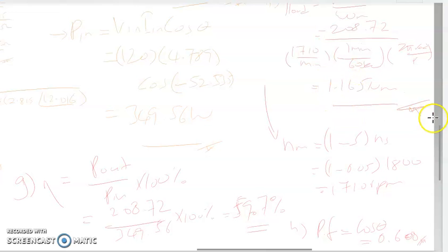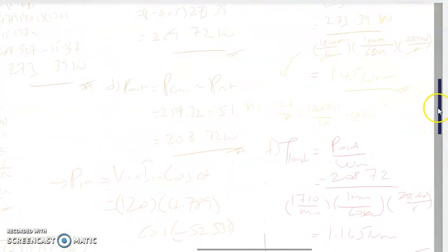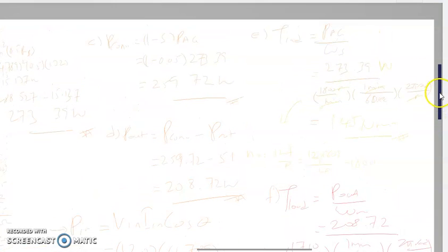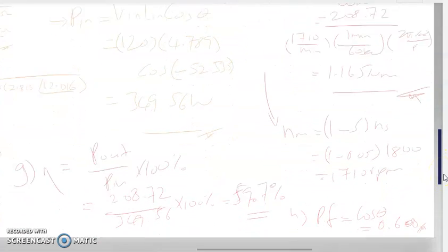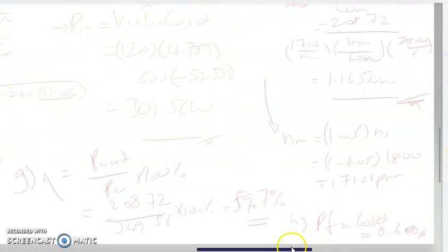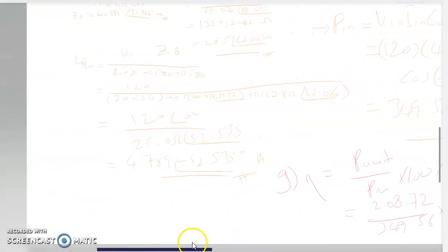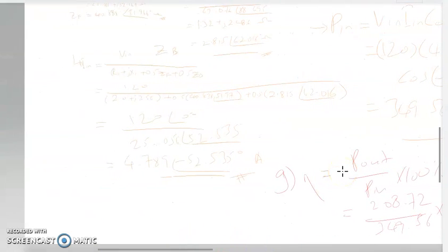Okay, we take note of the load torque here, which is 1.16 Newton meter. This is the load torque, the full load torque. This is not the induced torque, which is higher, but this is the load torque, meaning that when you operate at your mechanical speed, this is the torque produced at the load.